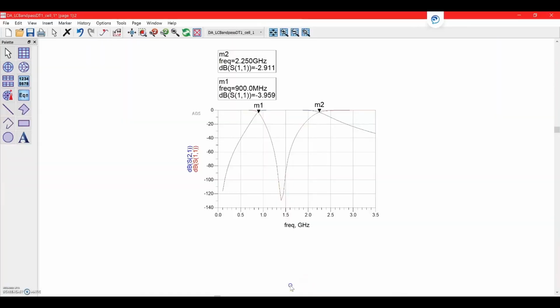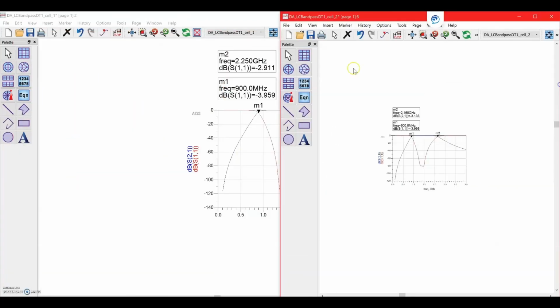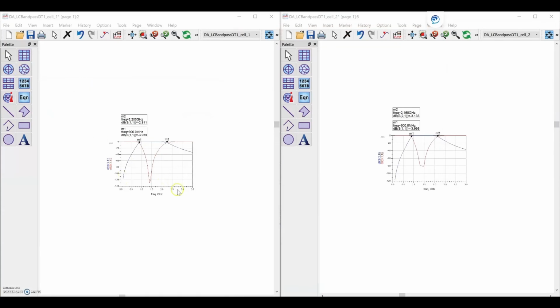So now if we pull up both simulations at the same time, we can see that they're actually quite close in terms of the cutoffs. The only thing that's different is going to be the second row, first column of the S parameters, where the ADS simulation is just slightly tighter than it is for the MATLAB calculations, which, if you think about it, makes sense, since with the MATLAB calculations, there are things like human error and rounding, versus when you do it through ADS, you're more certain that you're getting the best possible output for your filter.